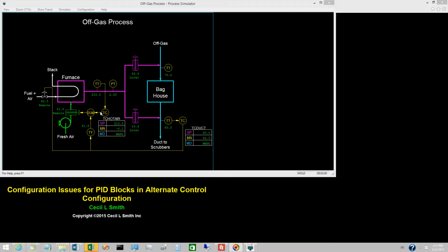For the modified control configuration, all outputs are expressed as percent open. We view percent open as the engineering units for the controller output. For most final control elements, the output range is 0 to 100% open. When a PID controller outputs directly to a final control element, the output in percent of span is numerically equal to the output in the engineering units of percent open. However, this is not generally the case when a summer is inserted between the controller output and the final control element.